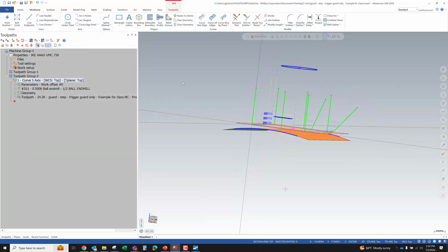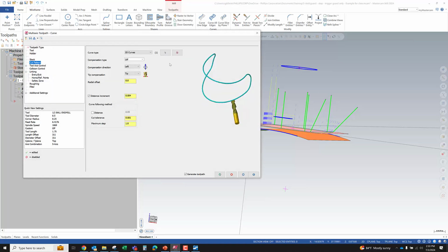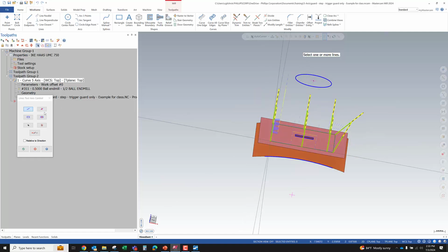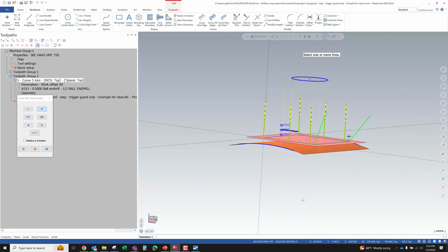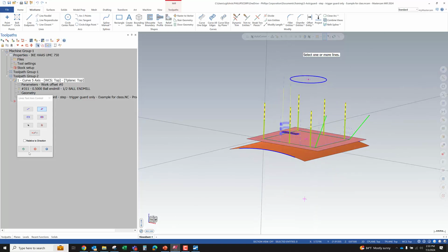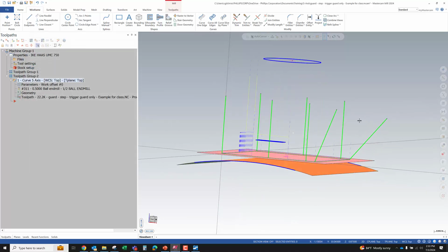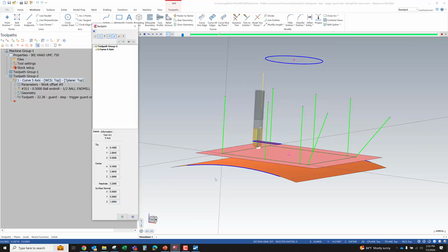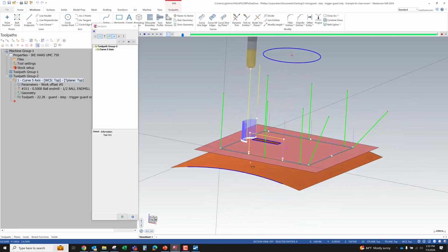Let's say, for example, we're machining this. I'm going to go back into the tool axis control lines. I'm going to click on unselect. I'm going to take out those 2 rotated lines. Say OK. Okay, what is this giving us now? It's giving us a 3-axis toolpath. I mean, it's vector-based, but it's a 3-axis toolpath.